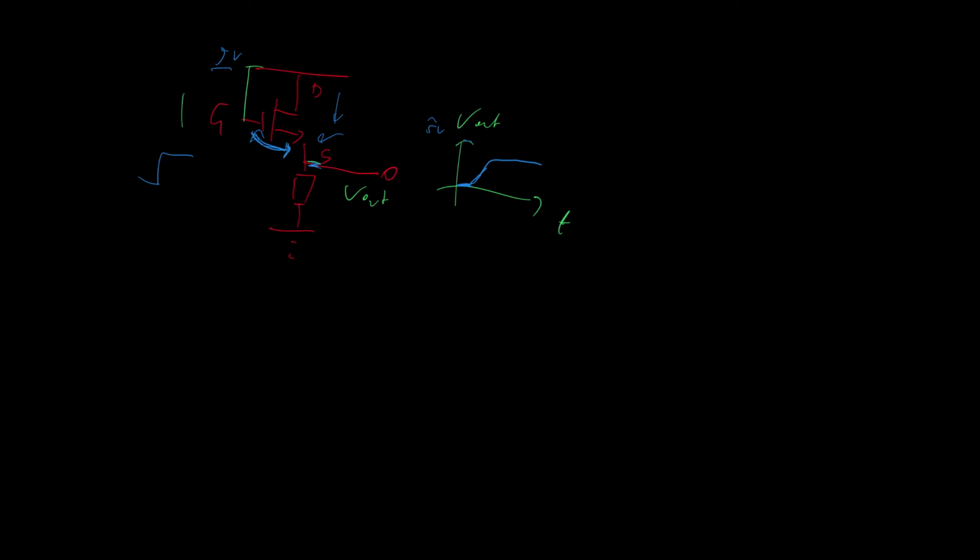The reason for the previous slide about the internals of a FET is that you might well say, okay, it's not really the gate to source voltage that determines whether this FET is on or not. It's the gate to substrate voltage. So let's be clever. Let's separate the substrate pin from the source pin and tie the substrate pin to ground. So this leads to our second attempt.